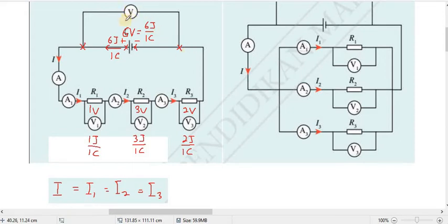So this voltmeter measures the total voltage. Why does this voltmeter measure total voltage? Because it measures from the beginning of the power source to the end of the power source. You see or not? In between here and here, there's nothing else that uses energy. So this is the total voltage.